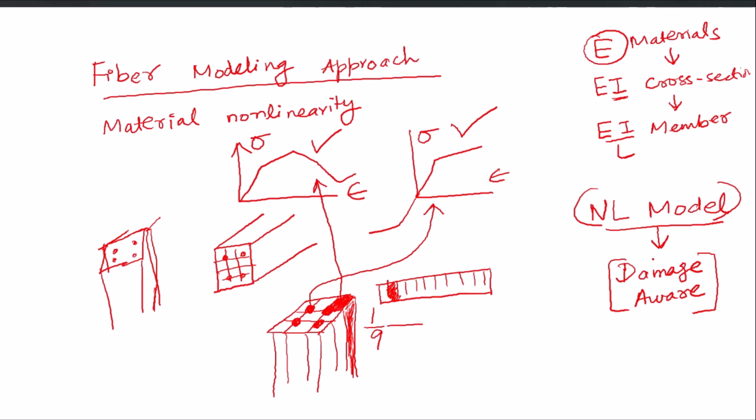And if I define each rebar as one steel fiber, then each steel fiber will have an area equal to the cross sectional area of that bar, and their location, which is, for example, this is the 2 and 3 axis of a particular cross section, and if a fiber is located at this particular corner, the location will be defined by two coordinates, one about 2 axis, one about 3 axis, and it will be at the center of this particular fiber.